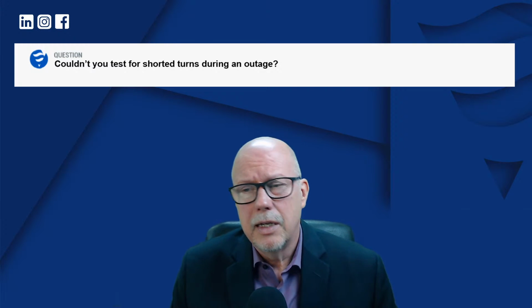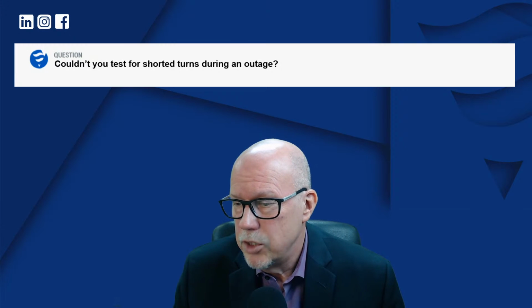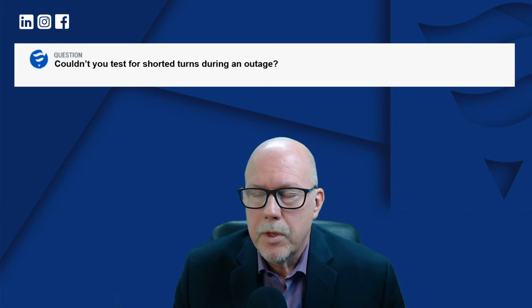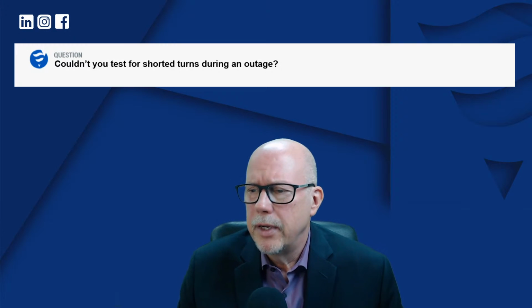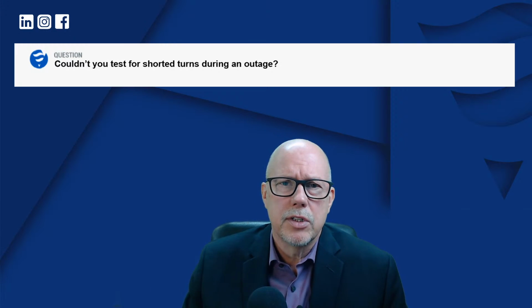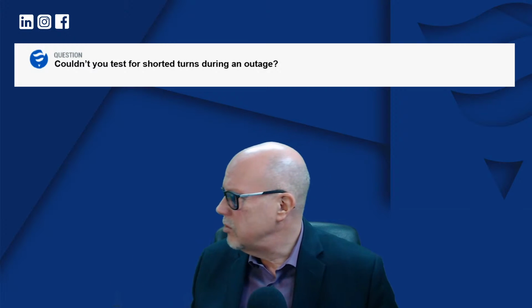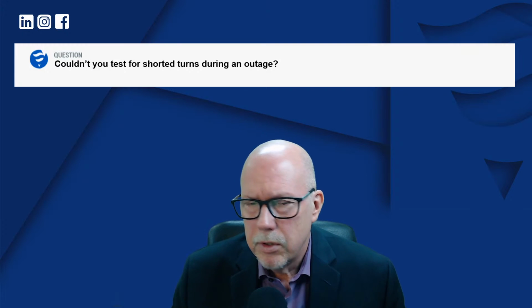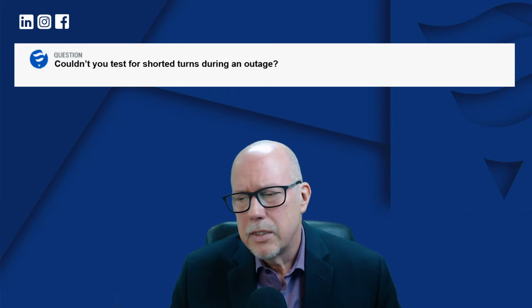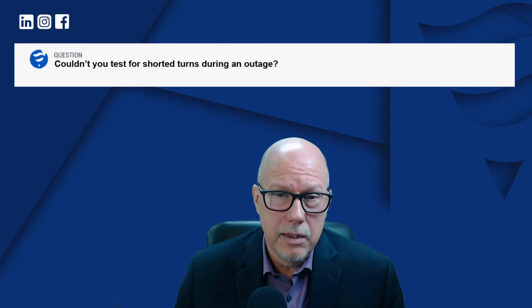Because the problem is that if you have a shorted turn issue, it might not show up when the unit is stopped and cold. Remember, the unit is operating at 3,000 or 3,600 RPM, so the amount of Gs is astronomical. I think it's like 5,000 Gs, some ridiculous number. And so the components are under tremendous amount of stress, and it is possible that the shorted turn only appears when you're in that condition.